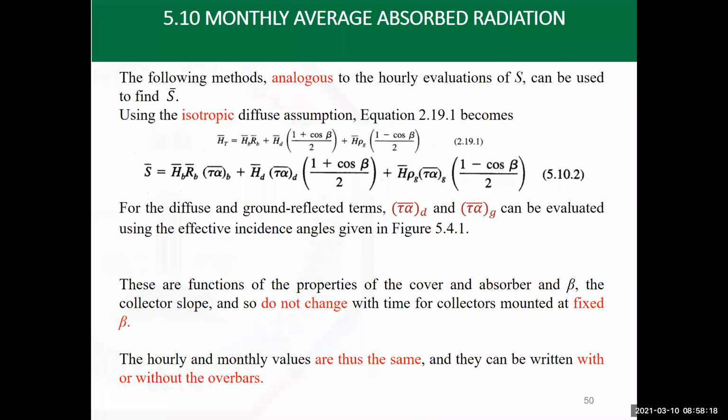You collect all of these values and put them together so that you can calculate, for example, for the buildings I'm going to supply, whether it is 50%, 60%, or even 100% of the energy needed by solar energy. Meaning you can have a building where you need hot water, and you say that 50% of the hot water needs are going to be supplied by solar energy, and the other 50% by electric heaters, or maybe by a boiler to heat the water and supply it.